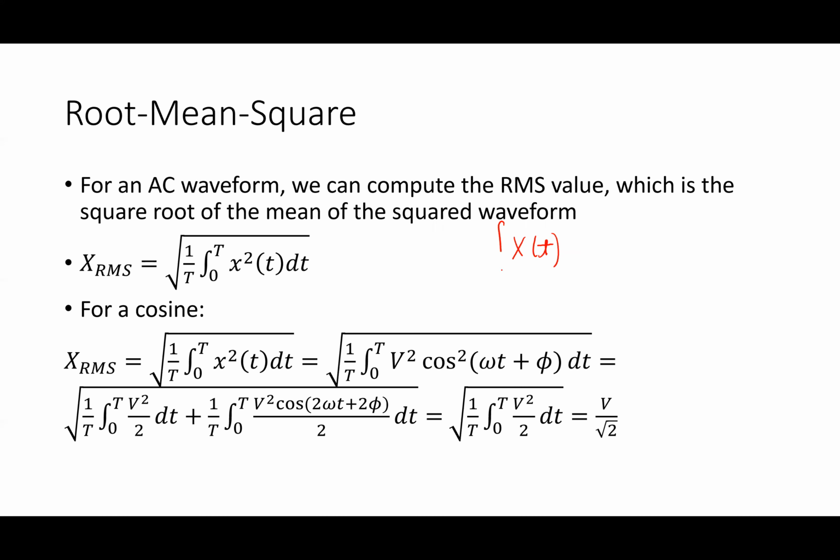Sum divided by a total number. The sum divided by the total number, which as Tone is saying here in the room, is basically the integral over a period. That's the summation. And then you divide by the total time that's encompassed there. This is the average value of x. So the reason we call this the root mean squared is because you take the waveform squared, you take the mean of that, and you take the square root of it, the root mean squared. It's used all the time, and it is the number that engineers pretty much always refer to.